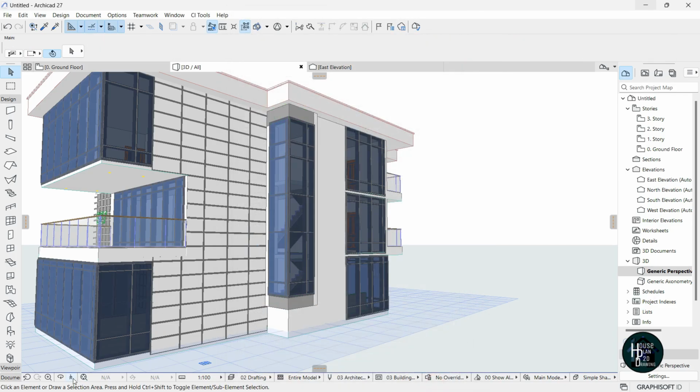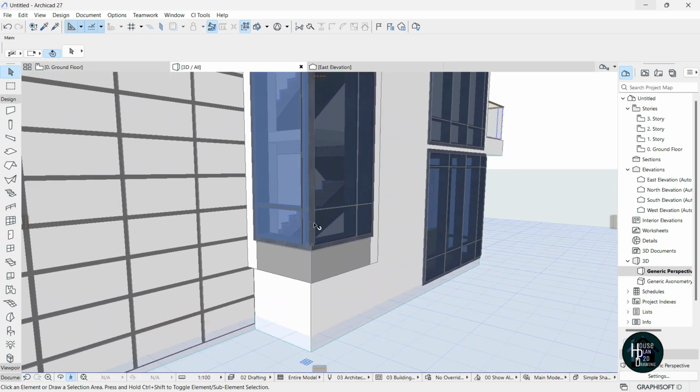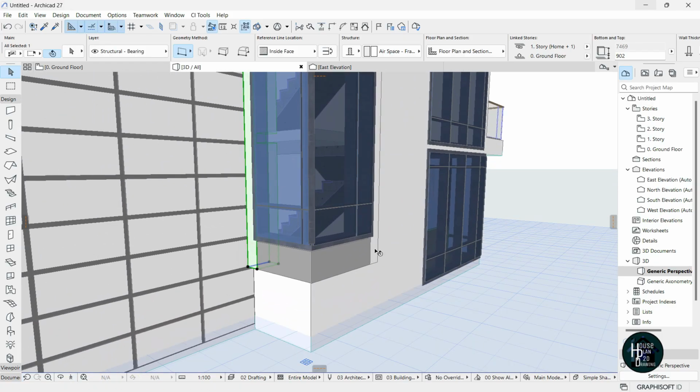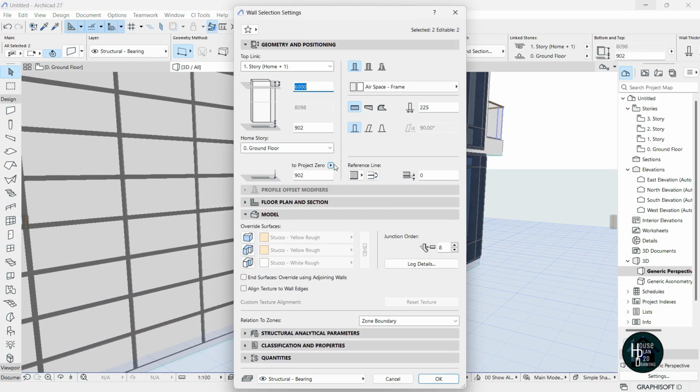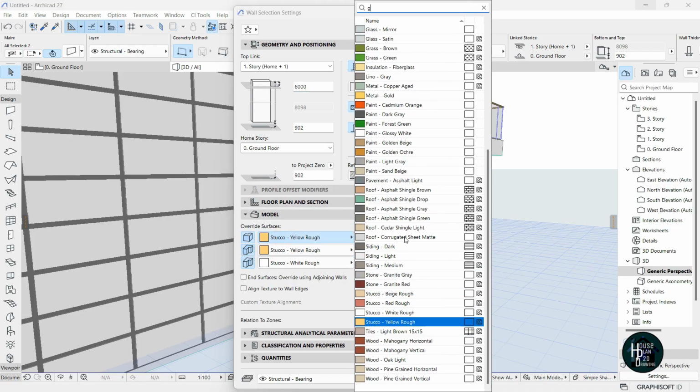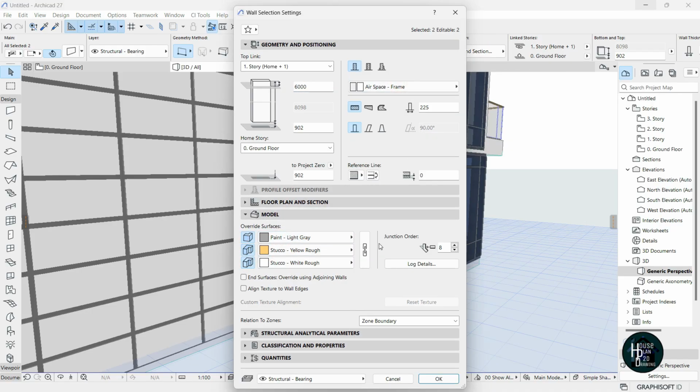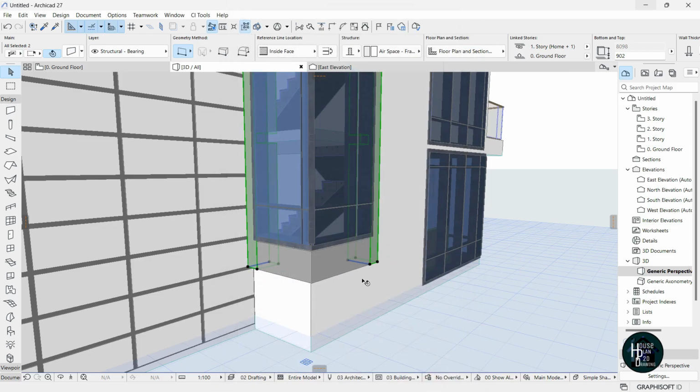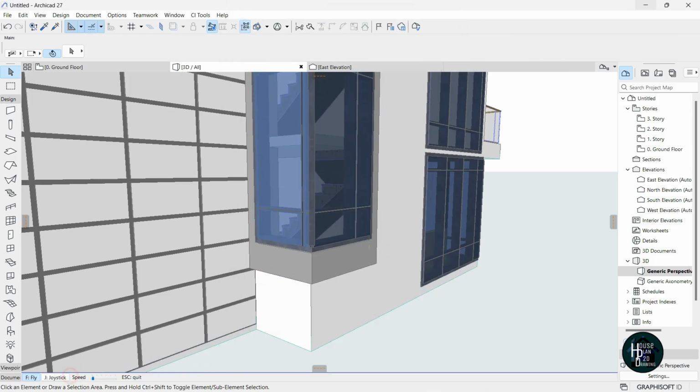So moving closer here, click this wall here, hold on shift, click this also, click on the settings dialog, highlight everything you see here, click this, and let's look for degree. Click this also, click on OK. So the design is going to come outside like so.